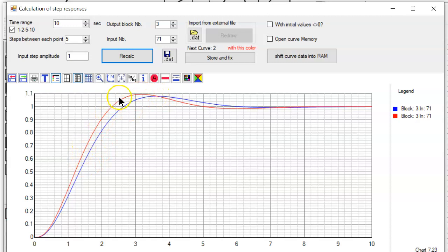Here it is a little bit faster. Final value is okay. PID-T1 has always a good final value. But you see here that is a true difference. Quality check. Is my identification acceptable? And you can see, of course, acceptable, not worse. A little bit faster, a little bit higher overshoot, depending on the specifications. You can live with this.